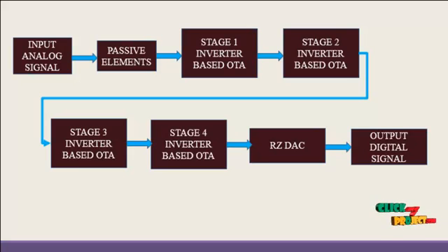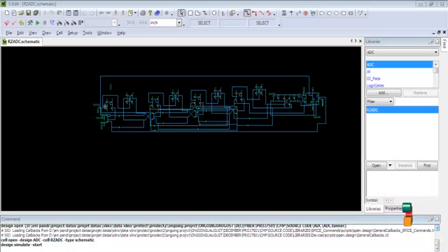There are several DAC architectures. The suitability of a DAC for a particular application is determined by three main parameters. The first one is resolution, the second one is maximum sampling frequency, and the final one is accuracy. Due to the complexity and the need for matched components, all but the most specialized DACs are implemented as integrated circuits. Next we see the running process of our product.